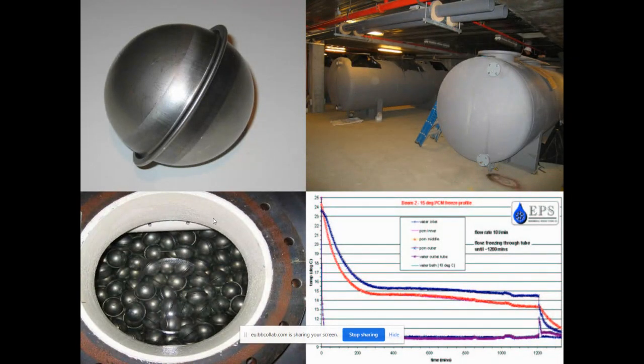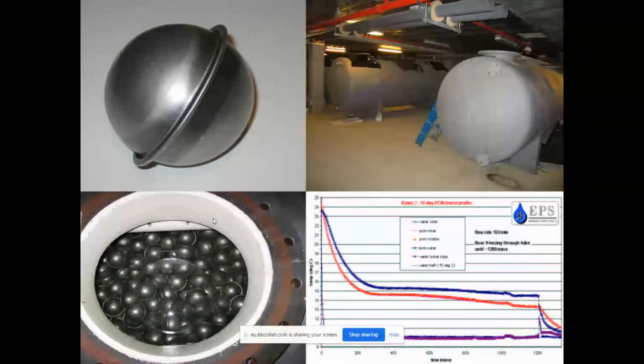And that cold air is cooled when the diurnal shift allows it. In other words, at night, or when there's a cold wind off the Southern Ocean. This is all picked up by the computer. So what we're doing is storing the cold energy in phase change.